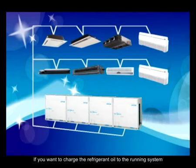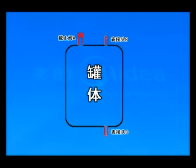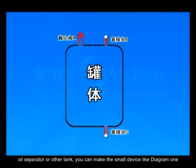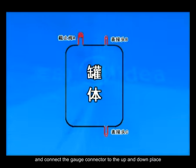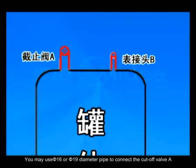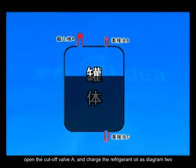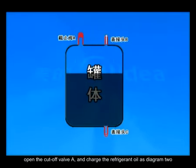If you want to charge the refrigerant oil to the running system, you can try this kind of small device. Using a small refrigerant tank, low pressure tank, oil separator, or other tank, you can make the small device like diagram 1 and connect the gauge connector to the up and down place. You may use Phi 16 or Phi 19 diameter pipe to connect the cutoff valve A. Open the cutoff valve A and charge the refrigerant oil as in diagram 2.